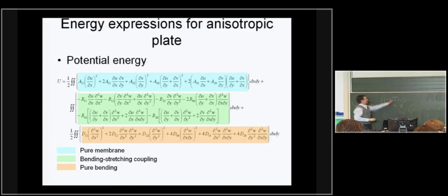So if one of these has already been eliminated, then instead of having E involved in the integrand, I will have the A matrix. So this top line involves the terms that we would consistently expect to find in a plate problem in isotropic material in a membrane kind of situation. The very bottom one involves now the curvatures. There is an equivalent to this kind of derivation that usually we know in terms of M squared over 2EI if it's a beam, and again this is integrated over the length of the beam.